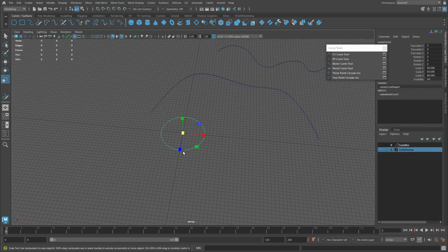I'm going to go ahead, select it, and delete it. If you want to delete any of the curves, just select them, hit delete. They're gone. If you create a square, this actually will be 4 individual curves instead of one continuous curve. So just be aware that it actually creates 4 curves. So I'm going to select them all, delete it.